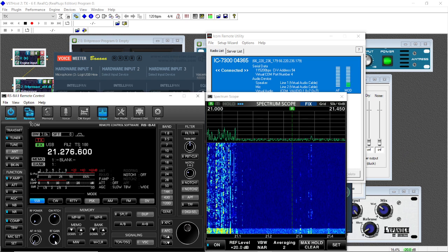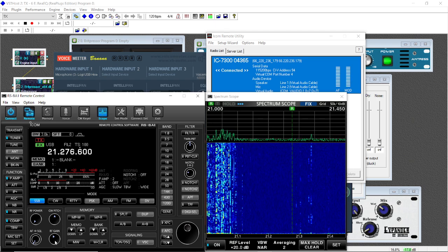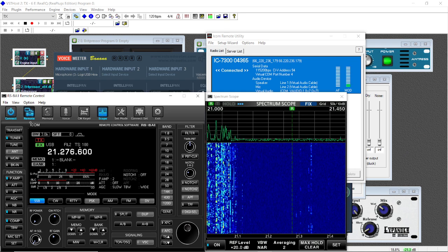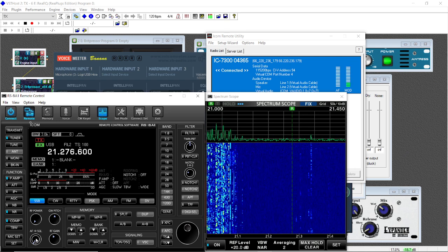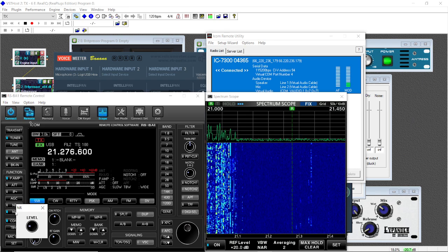What this allows you to do is it pumps up the audio so much that you can bring the RF gain down, like crush it. And then what you do is you use the AF, which sends the audio to the software, the RxDAP, and that's how it's processed. So you're stripping out a lot of noise. The noise reduction, I always run the noise reduction on.